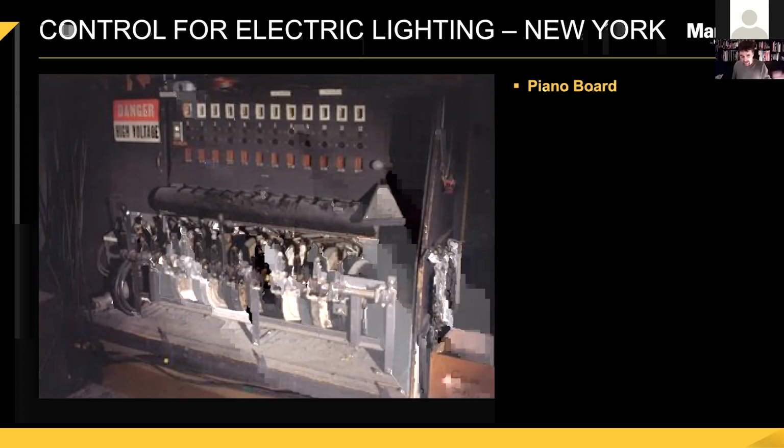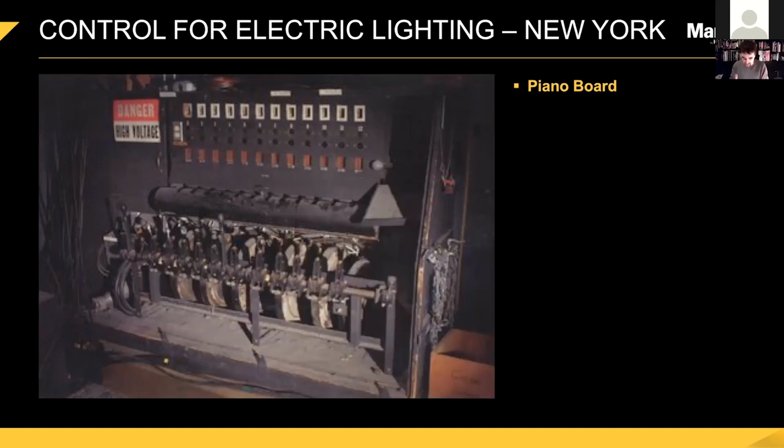Where we get into the then to now history of this is that even though they look nothing like the controls we use now, almost everything about the way we work on almost all of the memory lighting desks we use today comes back to these boards, because they're single preset boards, which means for each dimmer there is one lever that controls the level. And you move the levers to control the lights until you end up with a pretty state on stage.